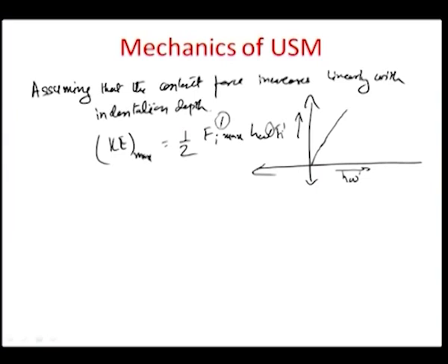the reverse force from the surface. After a while, once the full indentation has been realized, the force at that point can be treated as Fi dash maximum. Then you can assume that the grain slowly releases contact, meaning it flies off the workpiece surface and the force goes all the way to 0. So the area under this curve, the shaded area, is really the work done, the amount of work because of which the indentation has happened.